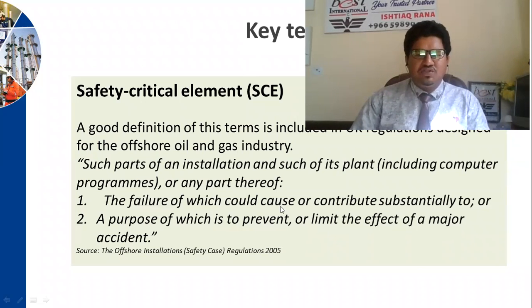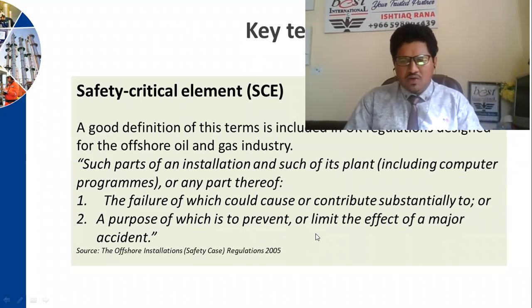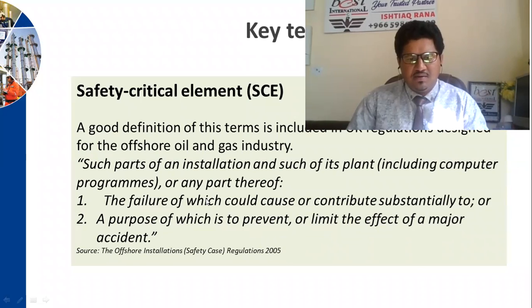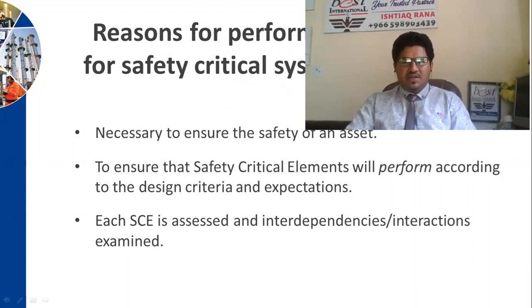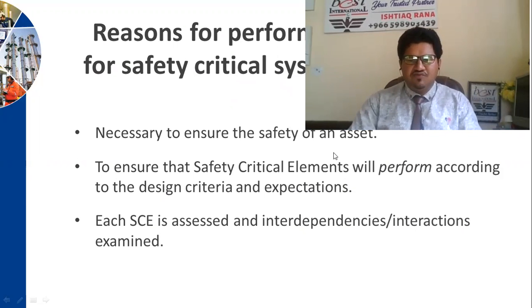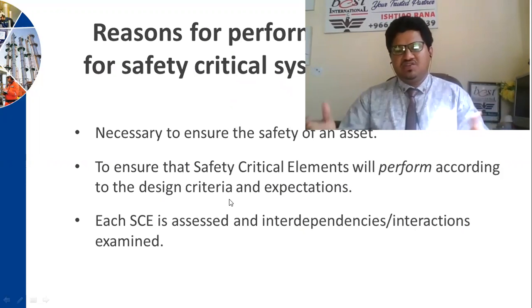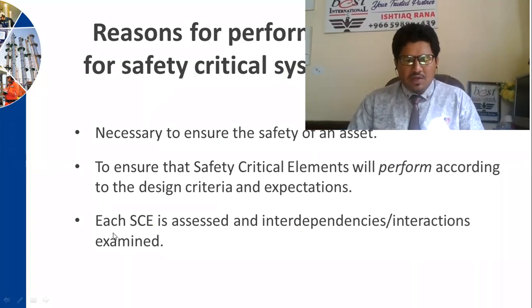The failure of which could cause or contribute substantially to a major accident, or the purpose of which is to prevent or limit the effect of a major accident. What are the performance standards for safety critical systems and why are they necessary to ensure the safety of an asset? They ensure the safety critical elements will perform according to the design criteria and expectations. Each SCE is assessed and interdependency interactions examined.